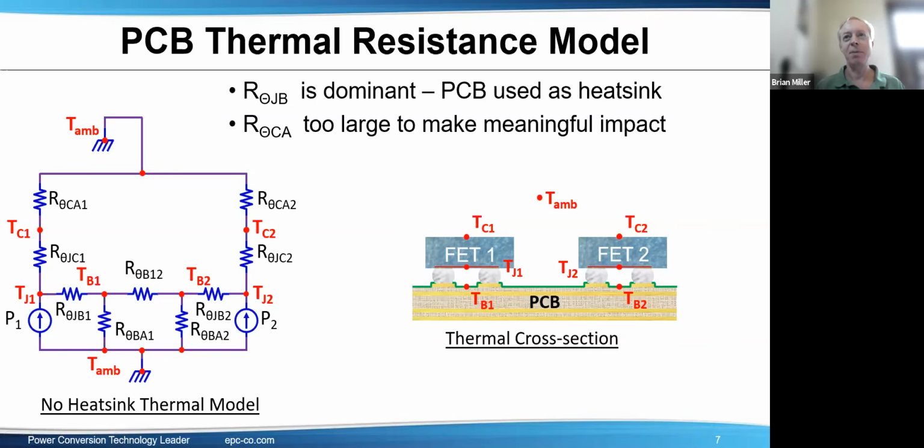It's just the same with EPC GaN FETs. If we were to put this in a package with a big piece of plastic over top and a layer here, the thermal resistance from the junction to the case, which would now be up here, would be greater, and it would lessen the thermal performance. That's just one reason we're not too thrilled about packages. You would pay for an additional piece of plastic and then reduce the thermal performance out of the top. But the MOSFETs don't have that choice, from what I understand. There isn't a way to really have all the connections in a lateral way on the bottom with an optimized power MOSFET.